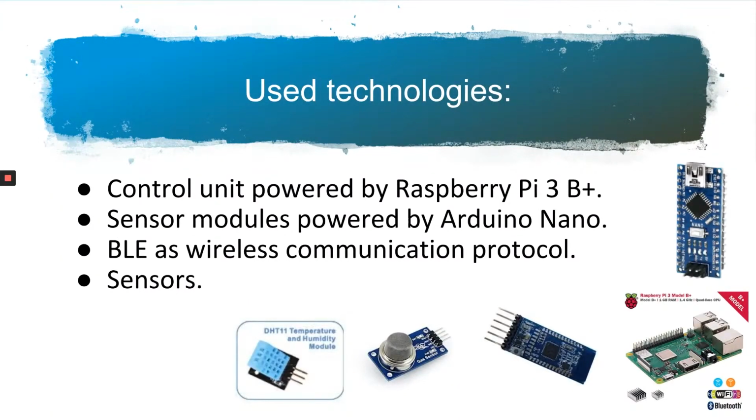The main components of our smart home system are the control unit and the sensor modules. For the system's control unit, we decided to use a Raspberry Pi since it's easy to set up and includes many desired features like Wi-Fi for internet connectivity, Bluetooth, and an actual operating system that simplifies the addition of a touchscreen display and the programming in general. Plus, it's extremely well documented in the engineering community and there's a lot of support out there.